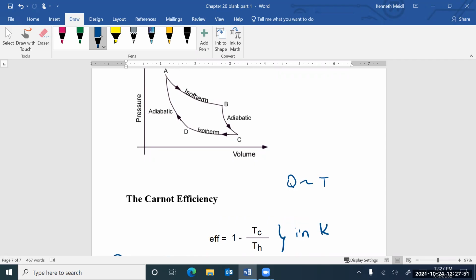And it's a long process. It's kind of like when you start looking at force problems, you go, oh, I've got to do a free body diagram. And then, if you've got vectors at an angle, you've got to worry about the components, add them up in the x direction, add them up in the y direction. You might have to put those results together and add the vectors up to get a result. And it takes a while to get through that. Going through one of these PV diagrams is kind of the same thing, right? You're going to start at A, go to B, go from B to C, and so forth. And there's going to be a little bit of physics at every single part of the cycle that you just have to work through.